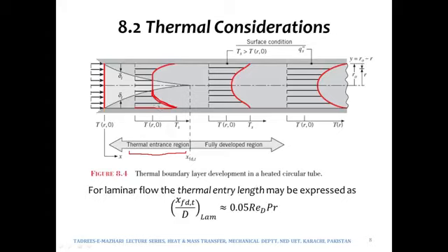Now consider infinite number of plates over here, all around the periphery of the inner surface of the pipe. So there would be in fact infinite number of small plates. You can consider it like that for the sake of understanding. So there would be a profile from each of those points emerging in this particular direction. So from the top it would be like that, right? And after a certain length, the flow would become more persistent. So its shape will become this shape.